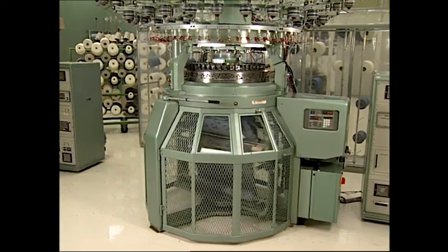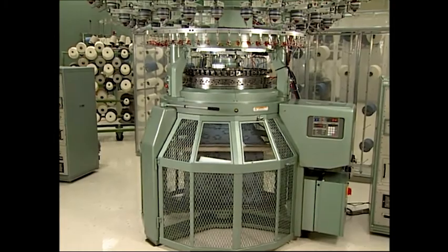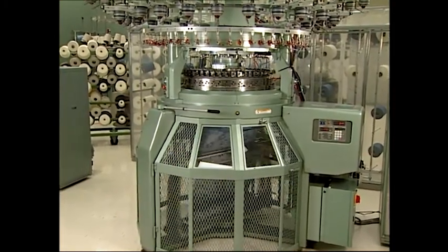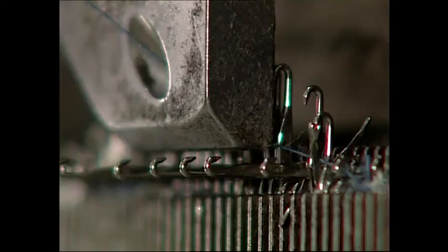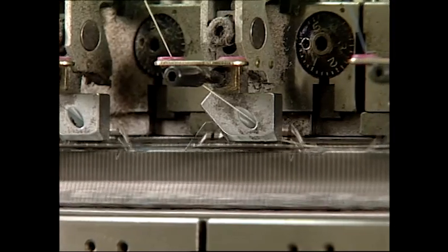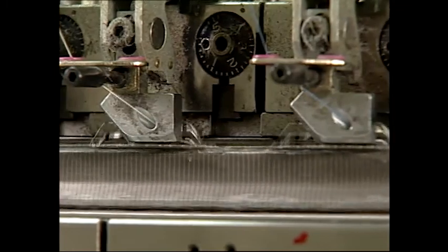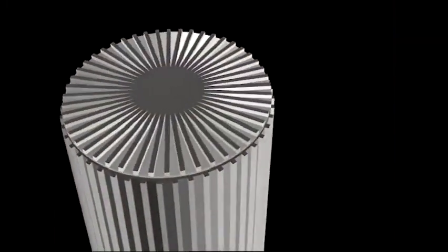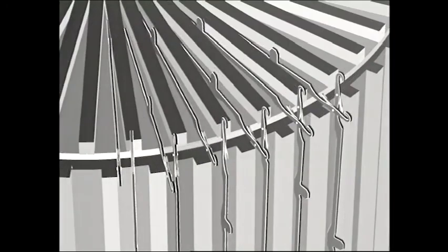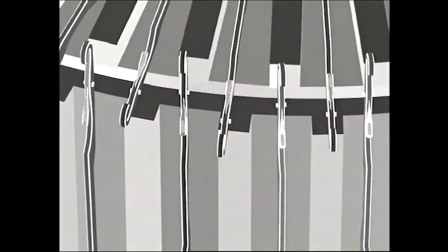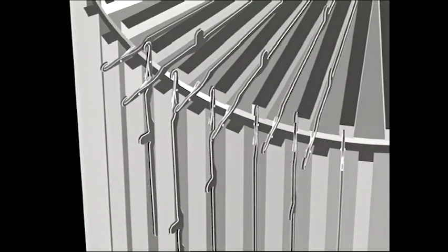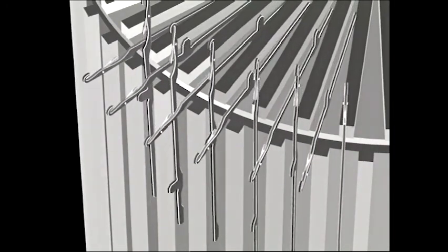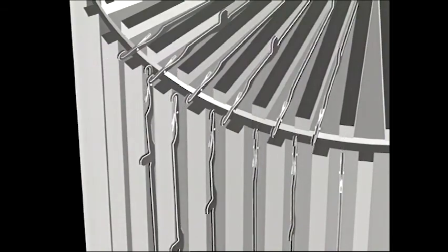Knit fabrics can be made with more than one set of needles. Single knit fabrics are made with one set of needles, and double knit fabrics are produced on two sets of needles. Rib and interlock are the two most basic double knits. Both use only the knitted stitch on all the needles. To accomplish this, a second set of needles is located in the dial, which is arranged above the cylinder. This dial has slots that hold the needles at a right angle to the vertical cylinder needles and will be of the same gauge or cut.